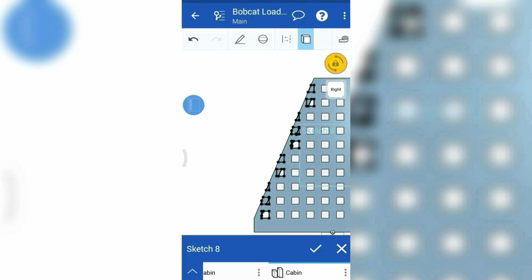Now we are done with sketch 8. Simply exit the sketch. Fill the material using Extrude add feature up to 10 mm in inside direction.